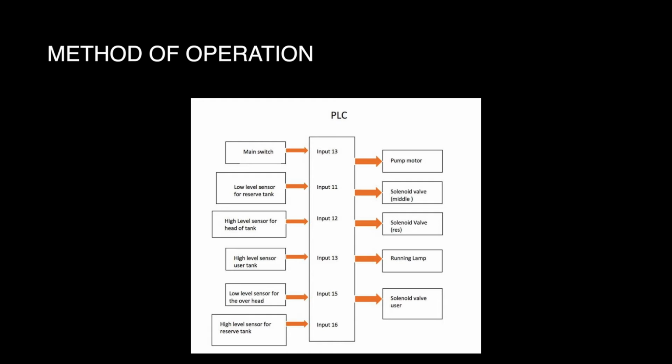Liquid level measurement signals are then sent to a programmable logic controller, also known as PLC, as the input module, with a set point of water level that has been pre-programmed in the PLC. The control system then determines the required signal to the output module, such as devices like valves, alarms and pumps. This then runs the action for optimizing the process based on the instruction signals sent from the pre-programmed PLC.